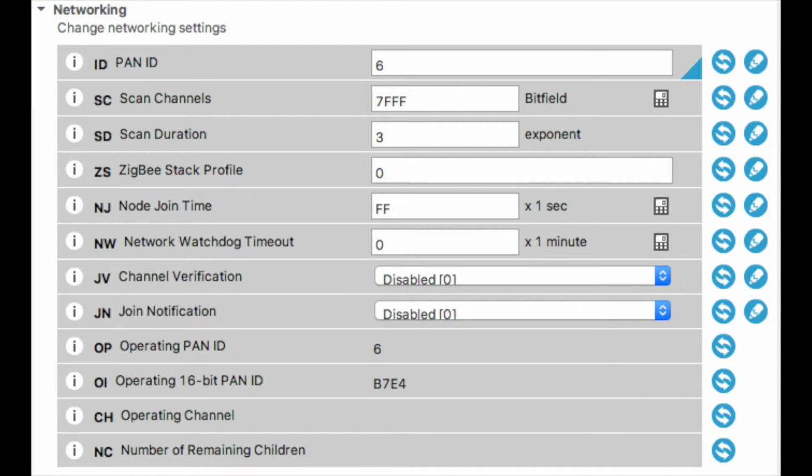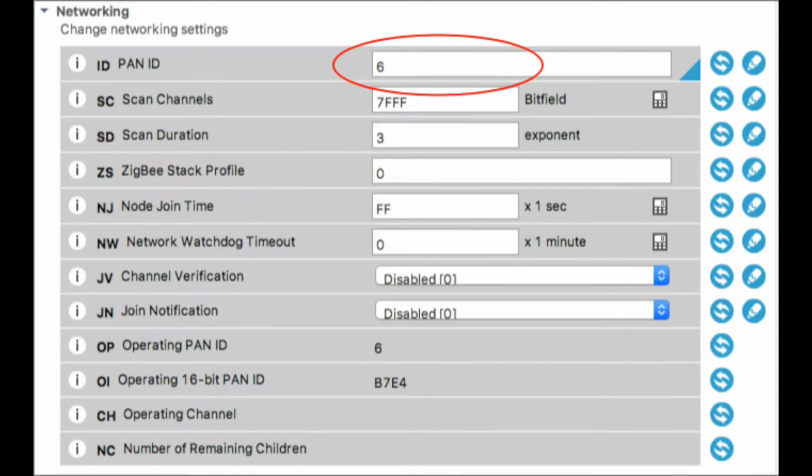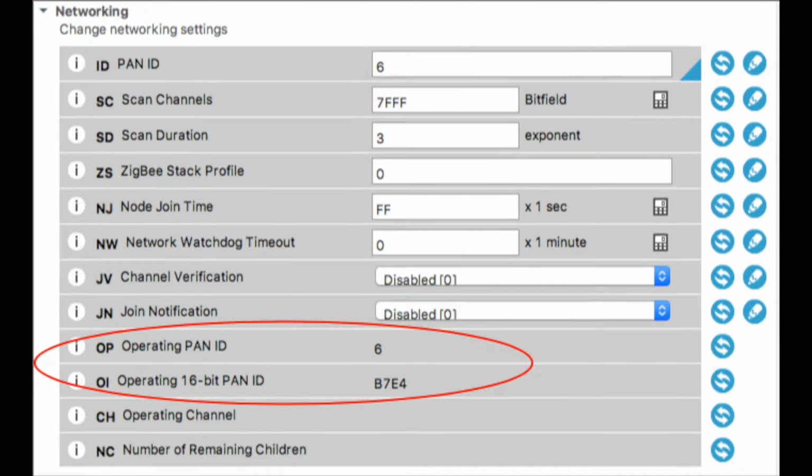So while designing our network, we encountered several challenges. The first challenge we encountered was a problem between the XBee communications. We set up the PAN ID, but they are still not communicating with each other. So what we did was we found out we not only need to reset the PAN ID, but also the operating PAN ID and operation channel.